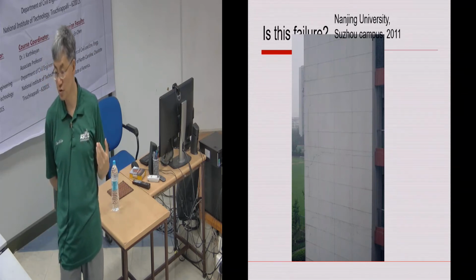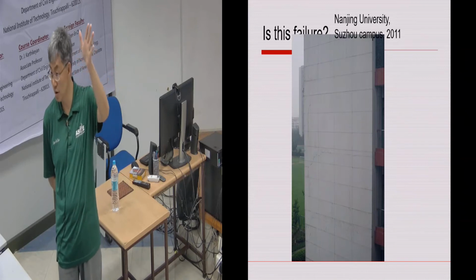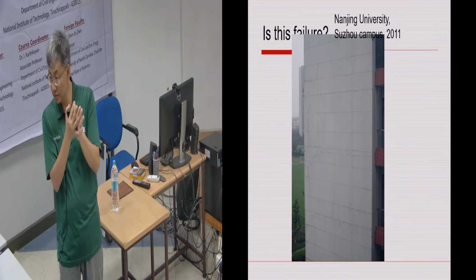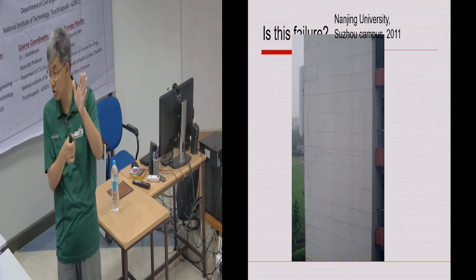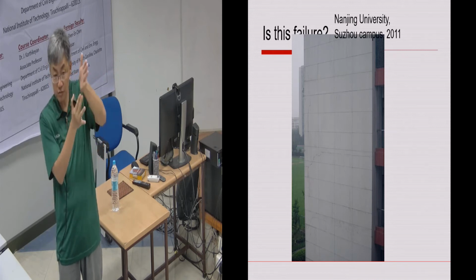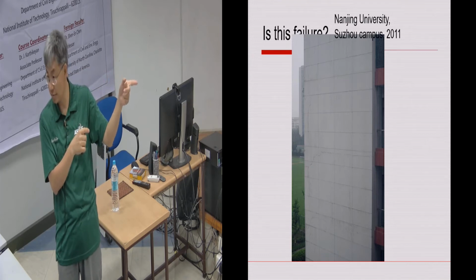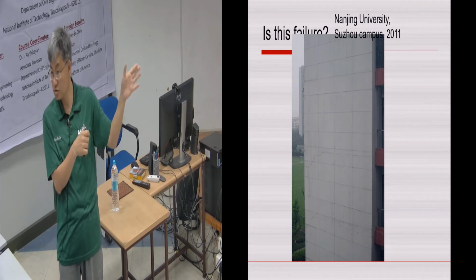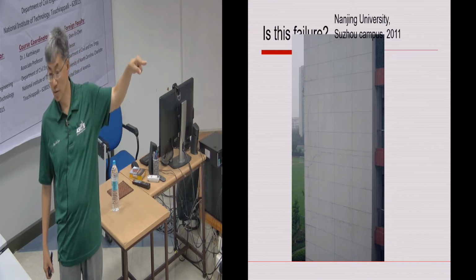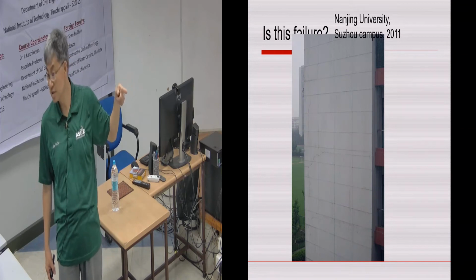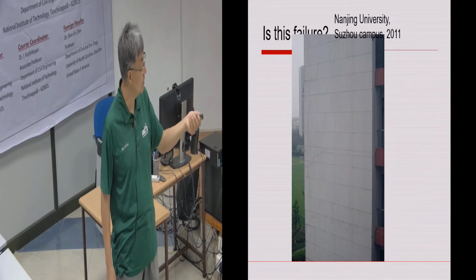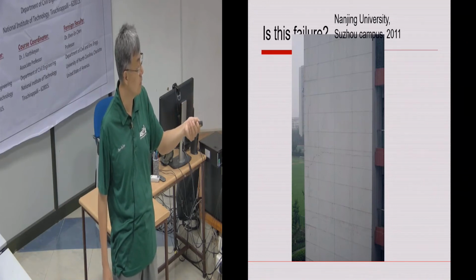Possible temperature differential, because all these tiles are bonded to the concrete structure, right? Yes, the stress either in the bonding elements or the exterior material would change. The differential displacement will cause the tiles to crack, because that's the weakest element. They are non-structural elements, right? That doesn't tell me that there is a structural problem with the beam or the column. Does that make sense? Okay. However, even with that, notice that this particular crack goes horizontal all the way through.